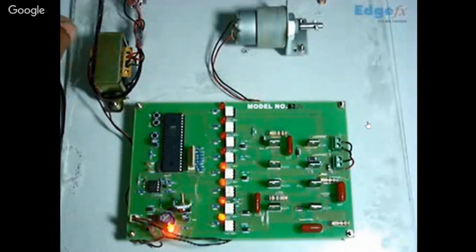And this is how, by pushing the button, you're actually changing the pulse rate to the thyristor. So actually the firing angle is changed, so automatically the speed is controlled there. At 90 degrees, when you're changing, it is the center point, that is, there is no voltage. So you can just shift over to the other stage. Okay, so this is the same way.